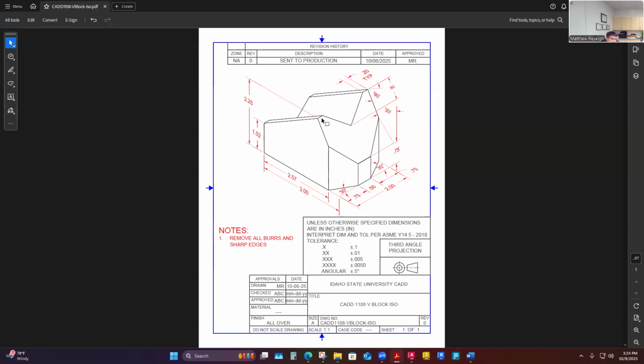And so when my eyeballs are on that edge, when I'm looking down, these surfaces are foreshortened. They're going down and away from me. And from this here down, this is all foreshortened. So this whole surface is going to appear foreshortened in my top view. And then I'll see this sticking out there. It'll be in perfect alignment with this, and that'll be a true length. That'll measure a half inch in my top view. It's just that this won't.